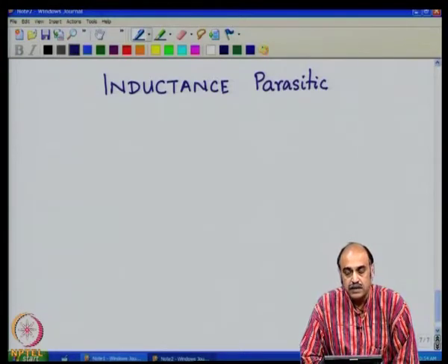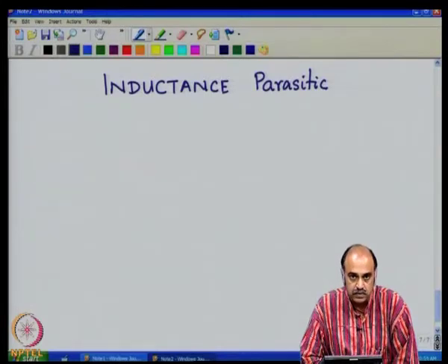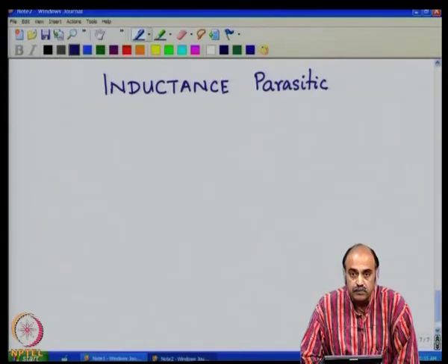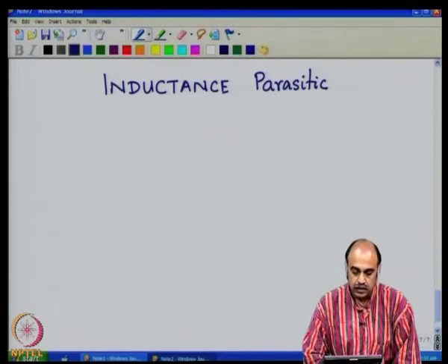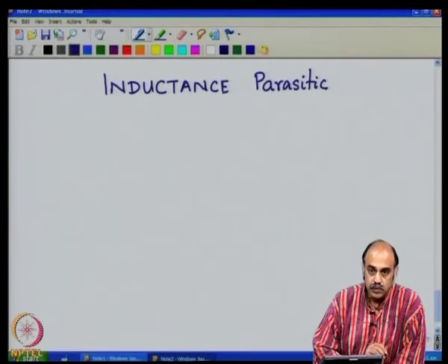These spiky currents have rise times, and these rise times are very high frequencies. So high frequency spiky currents flow through the grounds and supply lines and disturb the stability of the potentials on them, and this can really cause great havoc in high speed circuits. So, let us see what we would like to look at in the inductance.